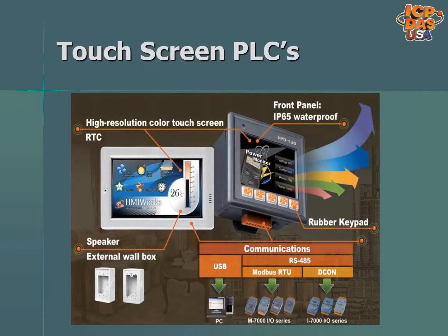Touchpads are touchscreen controllers that support Modbus protocols and are programmable in C language or ladder logic. They come with HMIWorks, a free development software. They come with a 2.8-inch or 4.3-inch display and can fit in electrical wall outlets. RS485 and Ethernet versions are available so they can communicate over Modbus RTU or Modbus TCP.